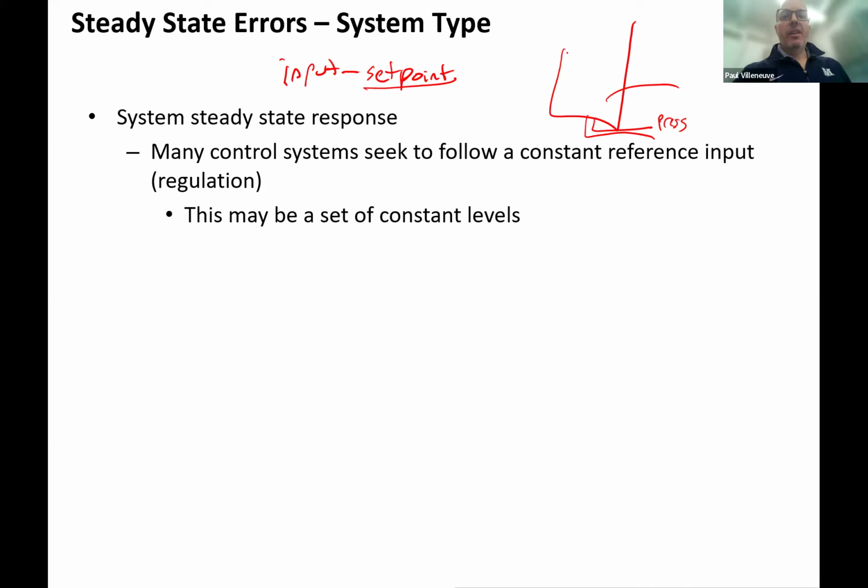Except, what if this is a pressurized tank? If this is an unpressurized tank, with just normal atmospheric pressure, then your pressure is pretty accurate. But there's a sneaky thing about pressure. Ambient pressure changes. Like today, it's rainy out there, so the atmospheric pressure is probably a little low.